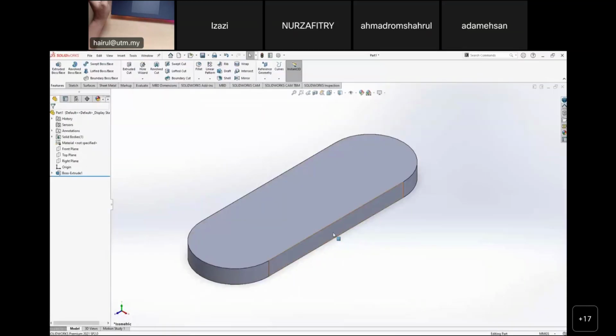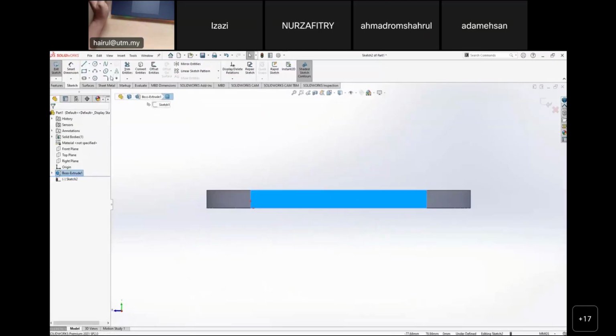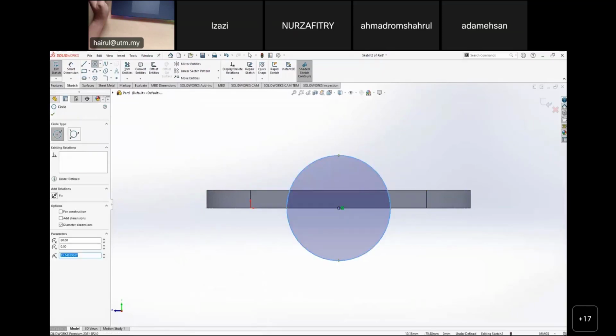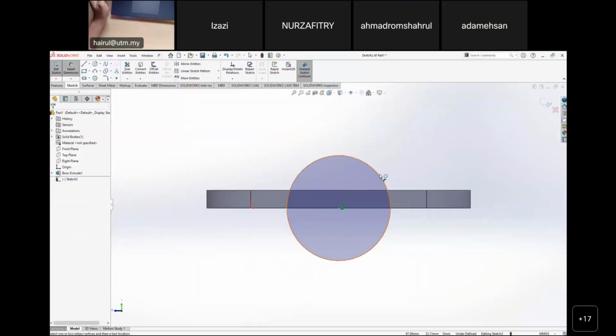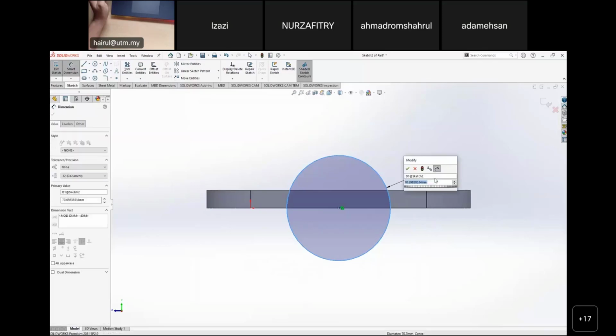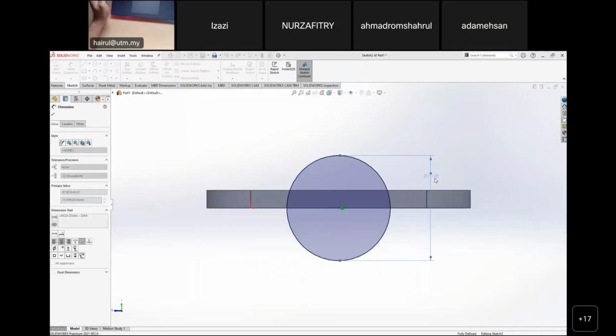We do the solid. So this one I have a plane sini. I have a plane. I make a sketch plane. Then I will make sure that it snaps at the center. This one is at the middle point. At the middle point here, it's not ini. You just consider yang ini. Yeah, this one middle point, and the radius is 36. So diameter is 72.